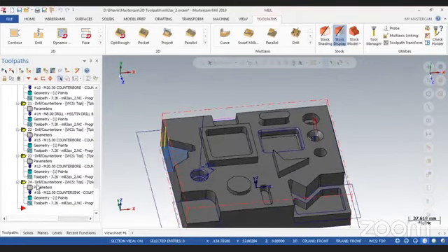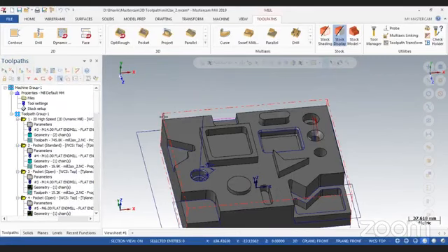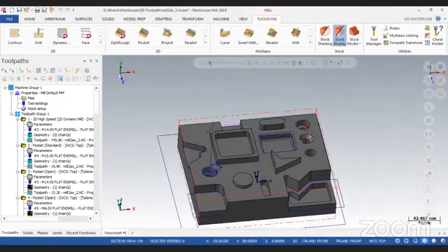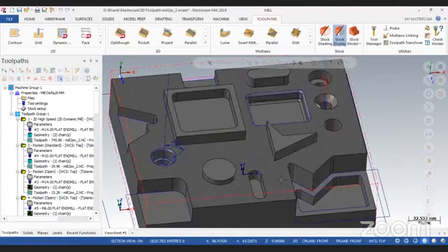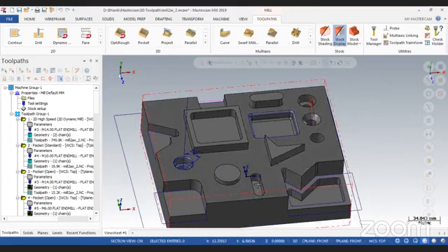So almost 24 different toolpaths are generated. We need to specify each and every detail, like which tool we want to use for milling this pocket, which tool we need to use for drilling this hole. So that is very specific. Selection of tooling should be very specific and accurate. So it will ultimately save your time.